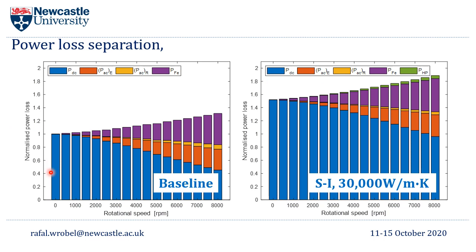The results have been normalized to the loss at low speed of the baseline machine, showing that system 1 allows for considerable improvements in terms of sustaining that additional loss for that 180 degree C hotspot winding temperature over the whole range of speeds.